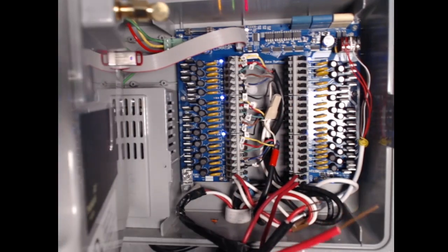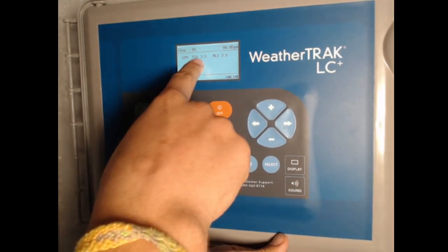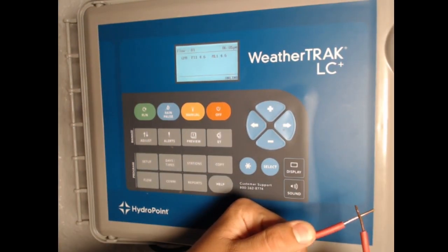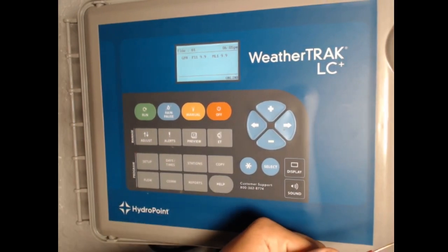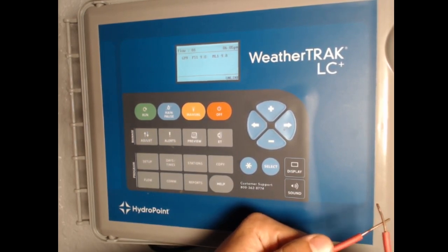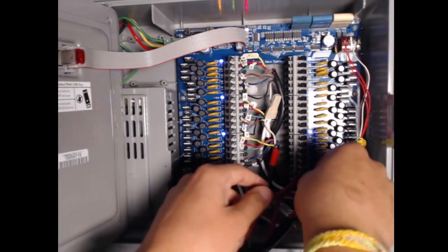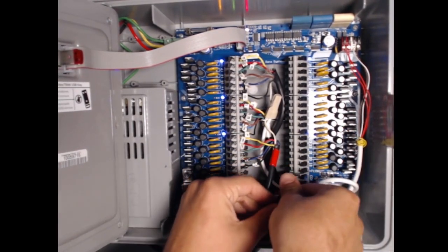And if I do that while examining my flow panel, you can see that I have read 3.5 gallons per minute. And as I tap faster, you can see that our flow sensor registers a higher gallons per minute. This should also give you a conceptual understanding of how a flow sensor works. The faster the signal the flow sensor sends out, the more water is moving past it. Now I need to unplug these dummy wires and plug my flow and communication wires back in.